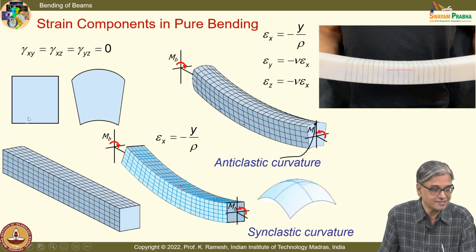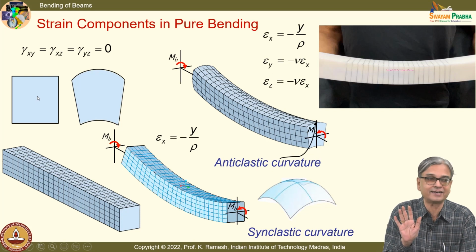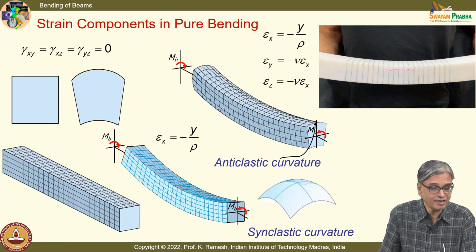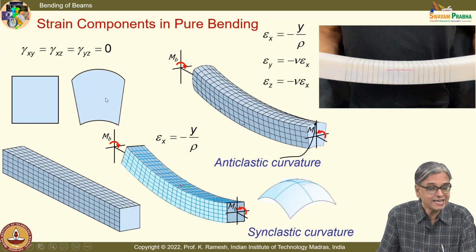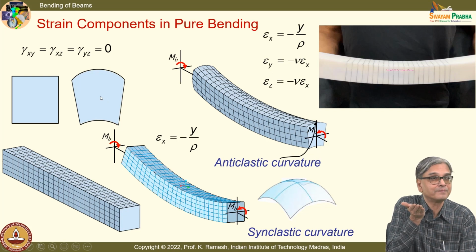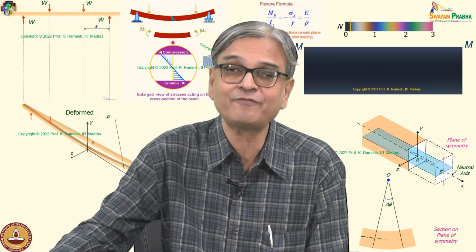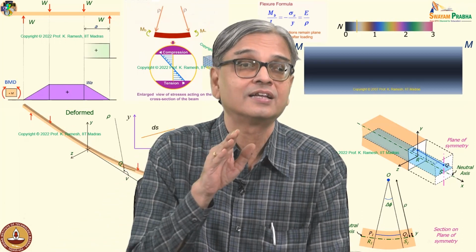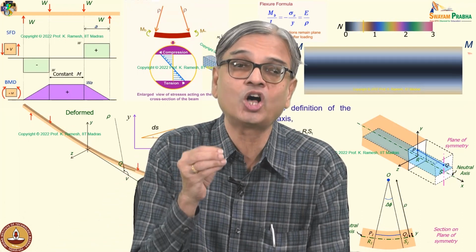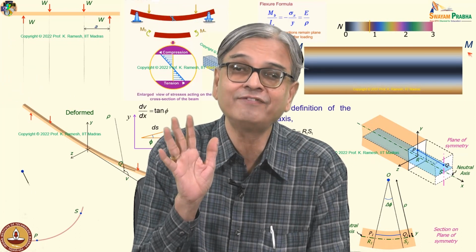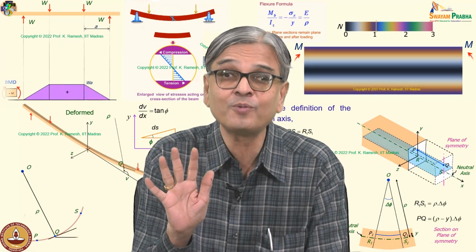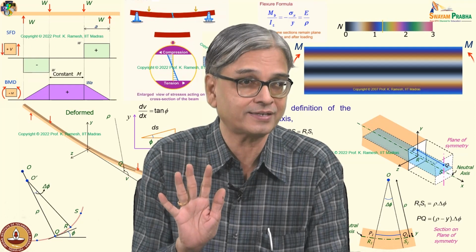If I take this as the actual bend of the beam, because of small deflection from the neutral axis, the y in undeformed and deformed will be more or less identical. Suppose I look at very large deformation, the height need not be the same, it has moved up. So you should also understand where I use the idealization of small deformation and live in the comfort of the undeformed configuration.